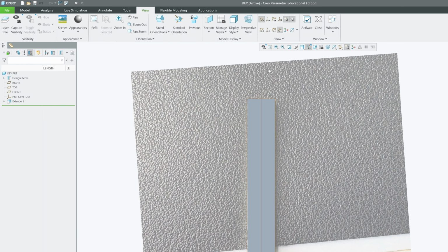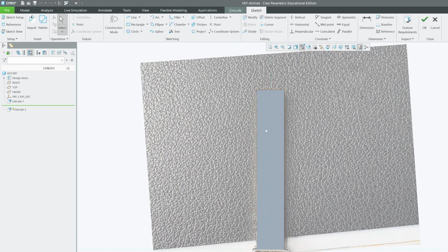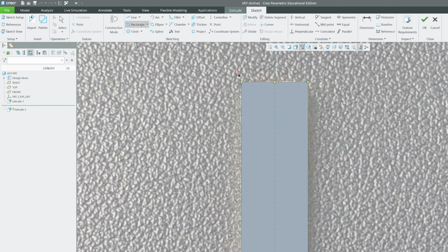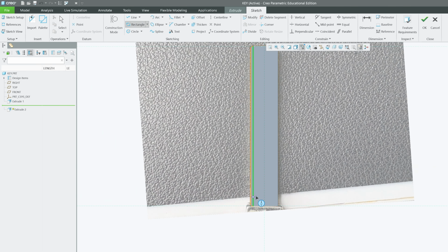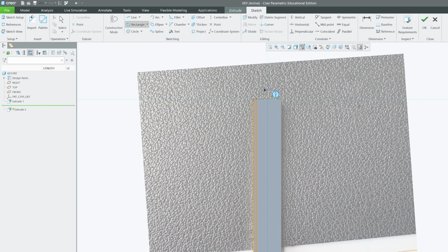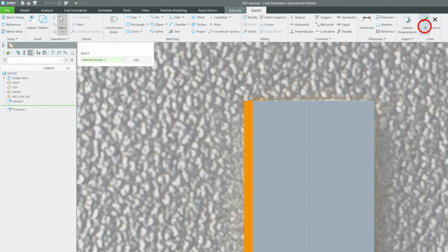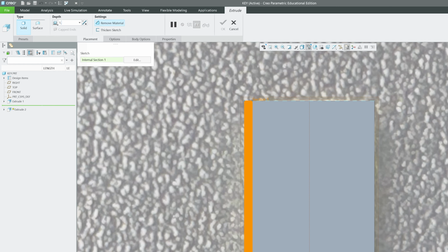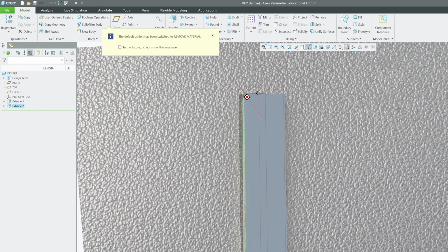Now again we can start, and let me start making another extrude. This one will be the small cut that we saw in the key. I'm going to give that cut here, and this cut is 0.4 mm. Let me write 0.4, and the depth of it is half of the depth of the key, which will be 1.5. And let's remove the material. Okay,